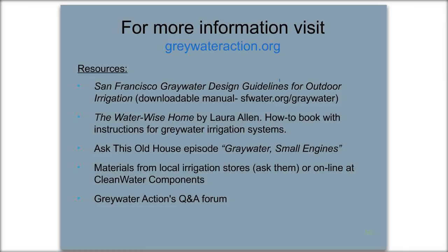Are there any really good toothpaste out there for use in graywater? Toothpaste? Yes. Is that the question? I don't know. The bathroom sinks are usually a pretty small supply, and unless it's really easy to use the water, they're not a great option because of all the toothpaste and there's more products going down the drain, and the quality is usually a little worse. So if your bathroom sink is already combined with your shower under the house and you can easily tap into both sources, it's fine to use it. It'll be pretty diluted with just a little bit of toothpaste. But if you have to go through a lot of work to get the bathroom sink, I would say you can just forget about that source because it's not very much water and the quality is a little bit lower.